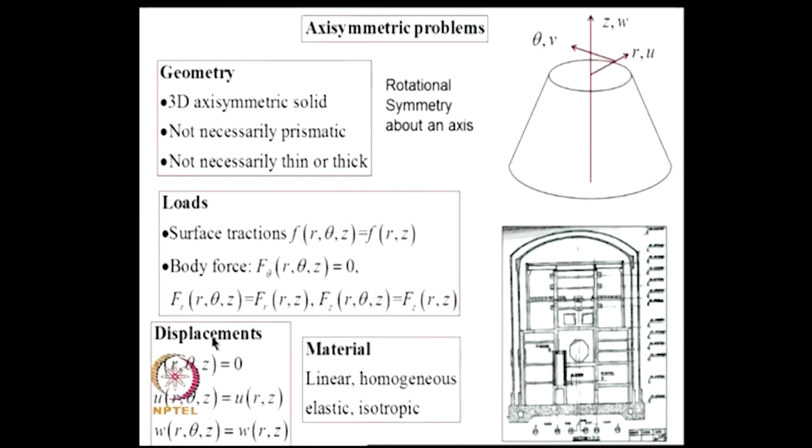So, there are 10 unknowns and we need 10 equations. These are the strain displacement relations, 4 in number, and the stress strain relations, 4 in number. The other 2 equations are obtained from the equilibrium equations. Whatever I showed here is replicated here, except that the terms which are 0 are now indicated in red. Consequently, one of the equilibrium equations is satisfied identically and we are left with 2 equilibrium equations.